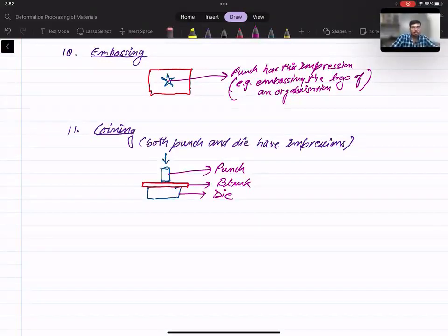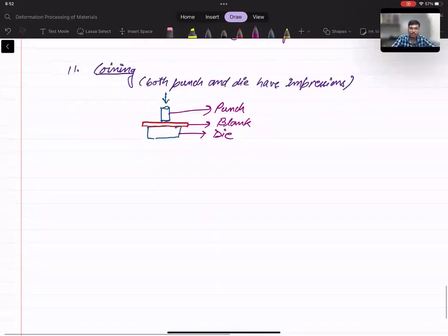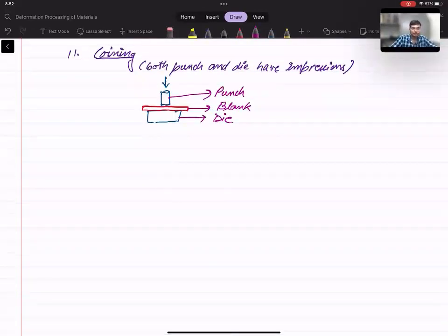So these were various forming processes till blanking. Before blanking, the processes which we saw were bending or stretch forming type of processes, and since these were left out, I have mentioned them here. These are basically forging type of processes. Again, these are sheet metal forming processes: blanking, punching, piercing, nibbling, etc. We have seen them now. For carrying out these operations, the force required can be determined. So let us see that.